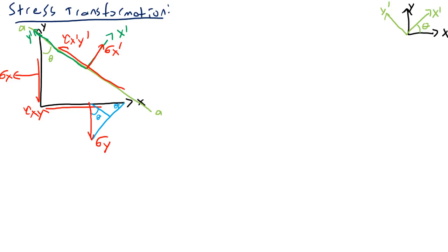The area here is dA sine theta. So if we're doing forces, the force here will be dA sine theta times tau xy.